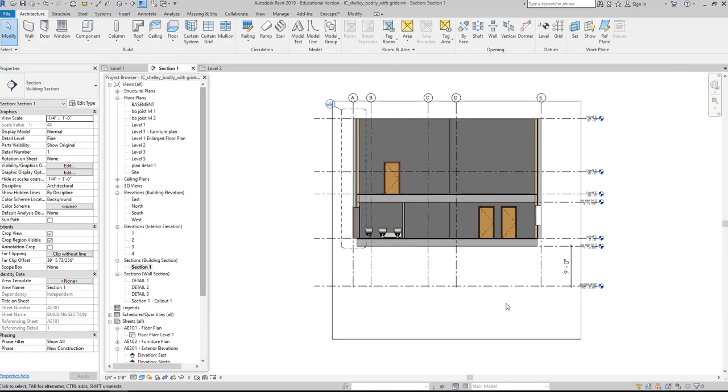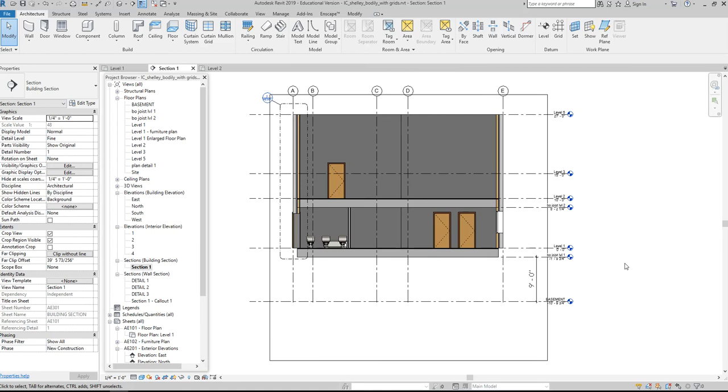Okay, so you see that as you continue on with your model, you start to refine things. Things have to be moved. You have to add new levels, right? There's more definition that continues to go into your model. All right, so looks pretty good. We know how to use the floor command. We know how to use sketch mode now at this point. We know how to assign a type of floor to our floor that we're going to generate. We know that when we use sketch mode, it has to be a closed region that we sketch.